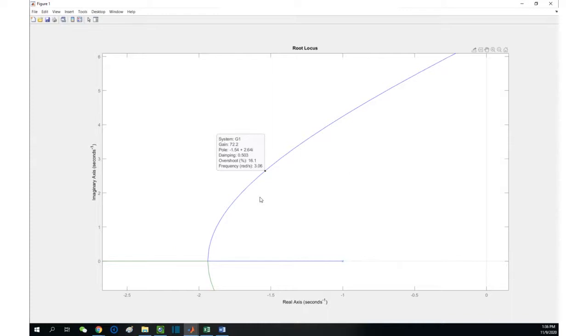And also from here, from gain of 72.3, what do we find are the closed loop poles of the original system? Of course, the dominant poles, these two. It's written here, 1.43 plus minus 2.64j, right? And if you are a little bit off, that's absolutely fine in the project. It's very tricky to locate exactly the point. You try, you know it.